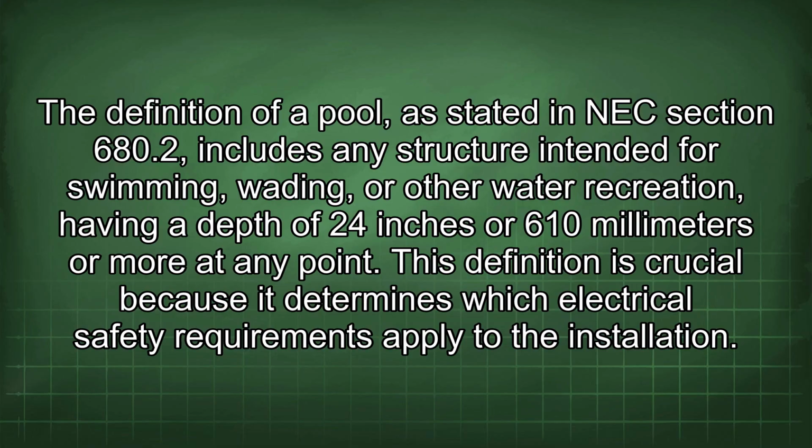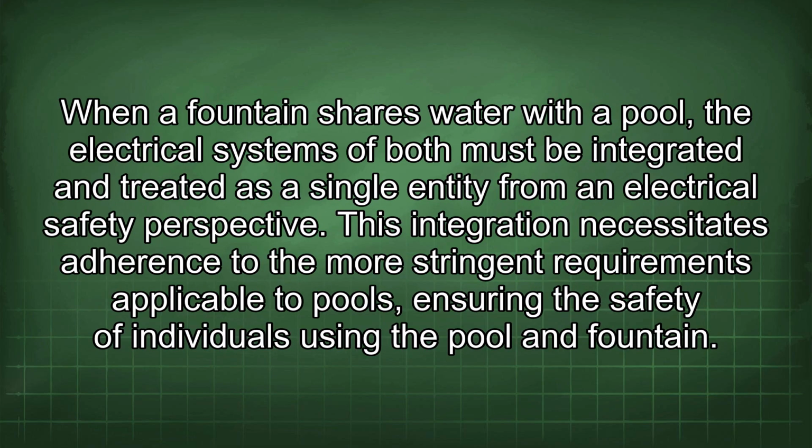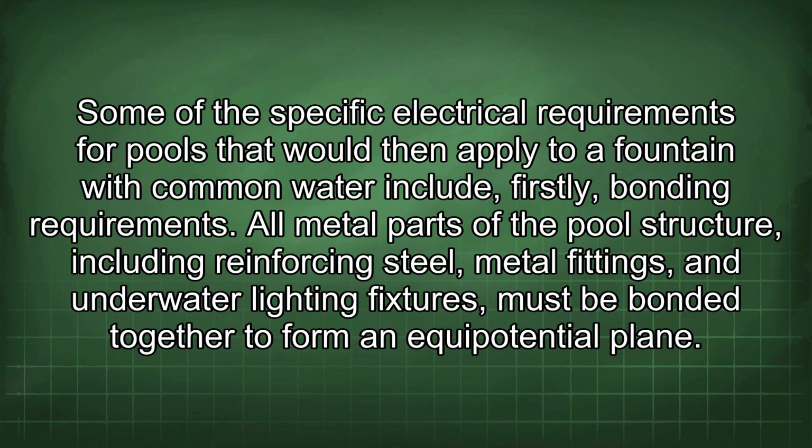This definition is crucial because it determines which electrical safety requirements apply to the installation. When a fountain shares water with a pool, the electrical systems of both must be integrated and treated as a single entity from an electrical safety perspective. This integration necessitates adherence to the more stringent requirements applicable to pools, ensuring the safety of individuals using the pool and fountain.